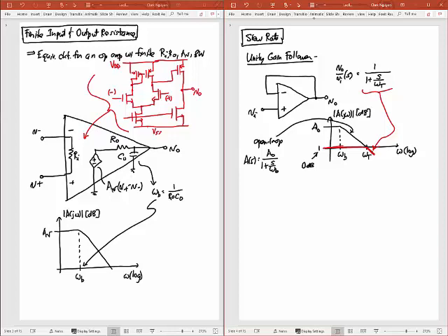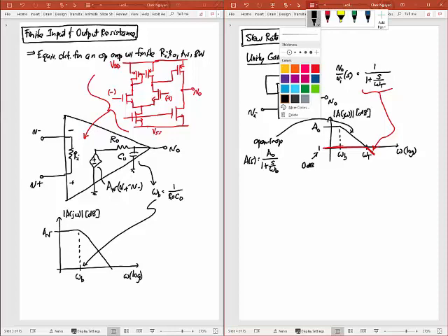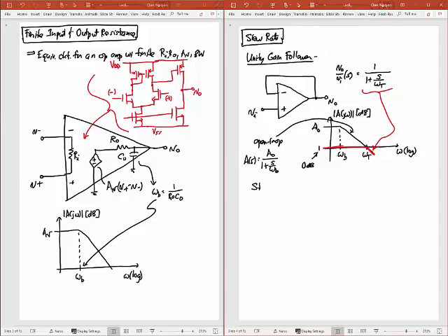And so, suppose I took this amplifier and it had this frequency response. So it has a very high cutoff frequency of omega T. But it still doesn't have an infinite frequency response. And so if I were to plot its step response, so the response to an input step function, then it will not repeat exactly that step function. And so you should know from 16 that the output of this thing, if I give it a step input, a square wave input, is going to be equal to what I'll call V0 of t equals infinity.